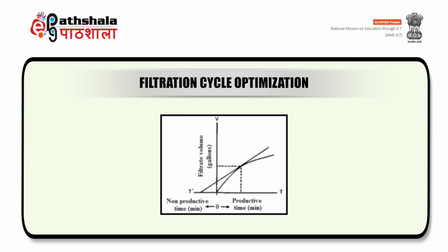The time lost in cleaning is offset by a return of high filtration rates associated with the new media. This point also can be calculated from the theoretical relationships for constant pressure or constant volume filtration. Data from lab equipment can be applied to the production units since the analysis is independent of filter area.